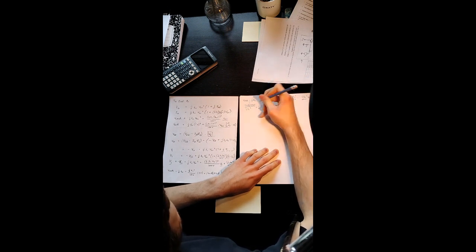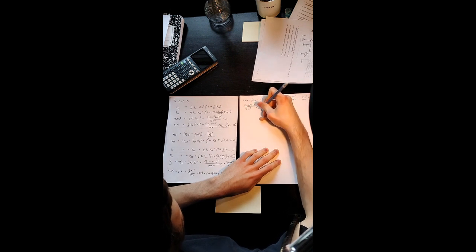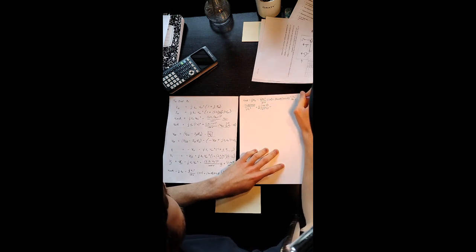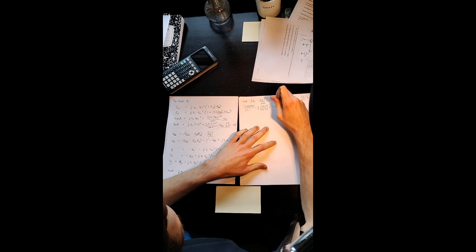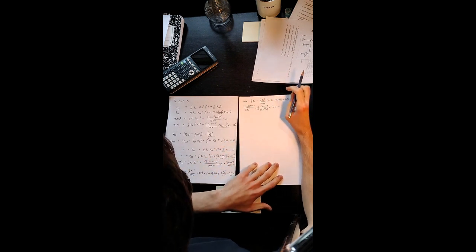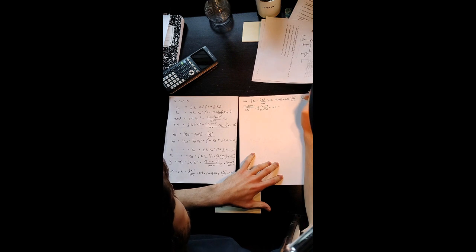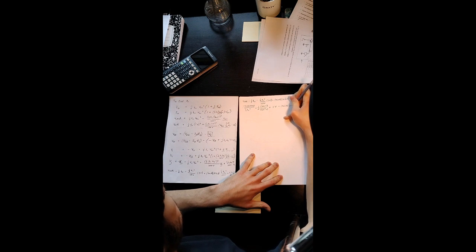I guess this becomes a plus, a double negative, over 1/4, and then Kn over Kn squared is 1 over Kn. Leave that there. Minus, and then these terms would cancel, so you would get a plus 5 volts, plus, and again these terms would cancel, and this becomes minus 4 milliamperes times 20 kilo ohms equals Vs.